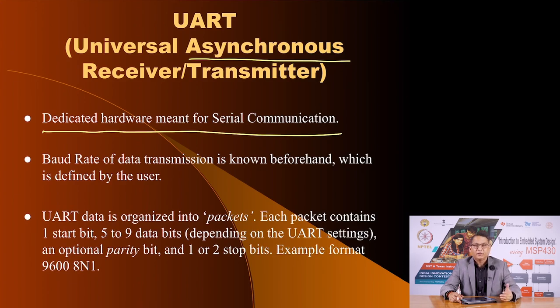Therefore some other method of knowing when one bit ends and the next bit starts has to be decided, and one method of doing that is to agree upon a certain time for which each bit will last. The resultant rate is called bit rate or baud rate, and the user has to define this before any communication can happen. And of course, both the devices must agree on that bit rate or baud rate.